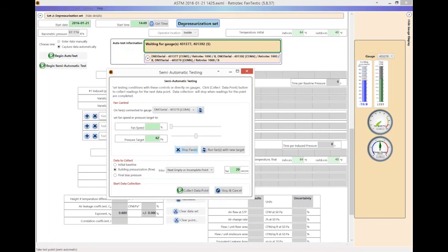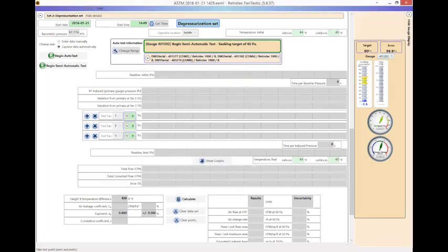Like, it's quite possible that a tube might be disconnected on one fan, the wire might not be connected, and you can run around and check all of your fans individually by simply changing the serial number over on the right-hand side for the display and over on the semi-automatic. So let's say, for example, you've got one fan at the top of a 10-story building. Instead of running back and forth or using radios or whatever, you can use this feature to run that fan throughout its range, check to see that it's working, it's giving results, shut it down, and then check the other fans before you press fully automatic. Does that make sense? It does to me.